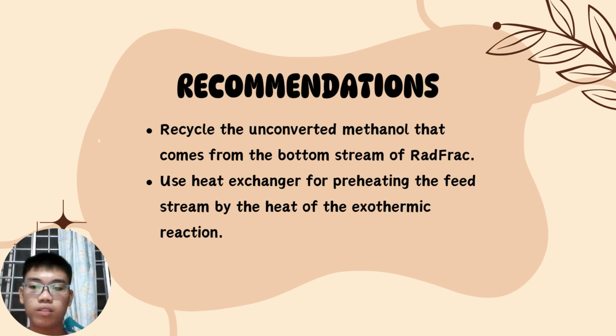In this study, there is still methanol content in the bottom stream of the RadFrac distillation column. So the unconverted methanol can be recycled back to the system to improve the overall process efficiency. And also, a heat exchanger can be used, as the heat from the exothermic reaction can be used for preheating the feed stream in order to decrease the energy consumption and also increase the overall energy efficiency.